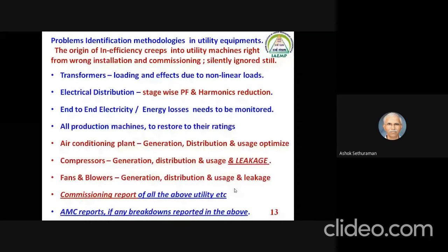Leakage is taking more, leakage is taking more in the compressors. In fact, in many of the up to 50 HP compressors we have seen, a 50 HP compressor almost gives around 250 to 300 CFM, but the leakage is happening abnormally. A quarter-inch leak almost goes to 100 CFM, whereas a quarter-inch piped hose takes only 30 to 40 CFM. You cannot allow the leakage to happen more in the industry, but leakage is bound to happen.